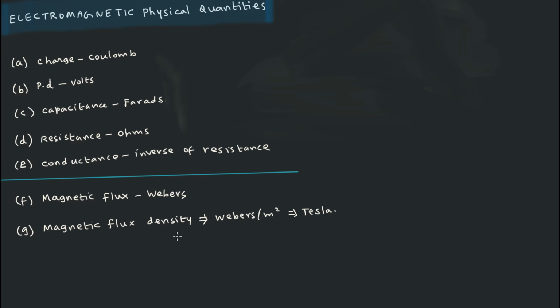The important point, once again, is the word magnetic flux density, and here you have a magnetic flux. The confusion is that many books use an alternate name called magnetic field. But there is a trouble here. Magnetic field has 2 different meanings depending on whether you describe it in a material medium or in vacuum. So if you don't want any confusion, it is always better to use magnetic flux density if you are going to express in Tesla, because there is another unit which we will see later. The unit for the magnetic field, for example, is ampere per meter.